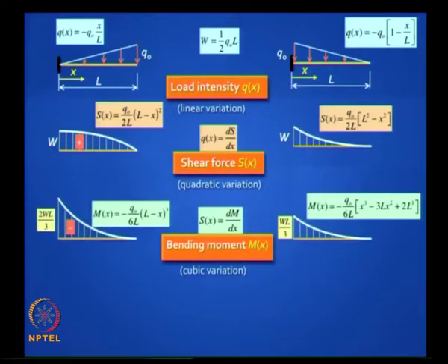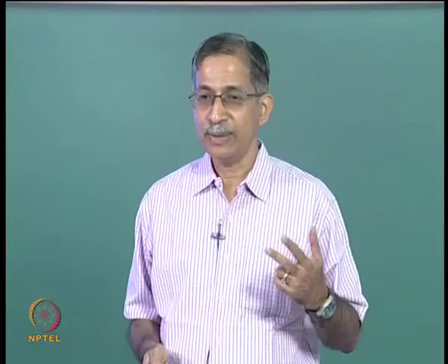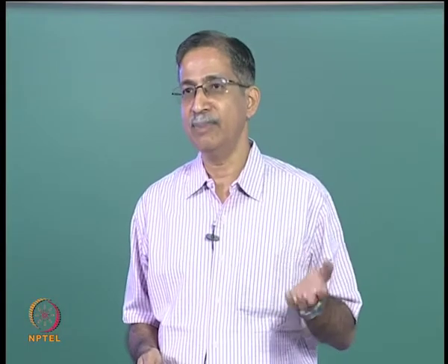What about the bending moment diagram? Well, it takes this shape. The slope of the bending moment diagram is the shear force, and the shape of the bending moment diagram is similar to the shape of the curvature diagram. All you need to do is to divide the bending moment diagram by EI and you have got the curvature diagram. You integrate the curvature diagram twice, you get the deflection diagram after you apply the boundary condition.